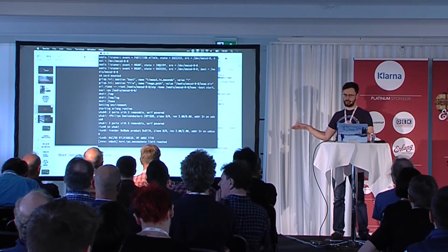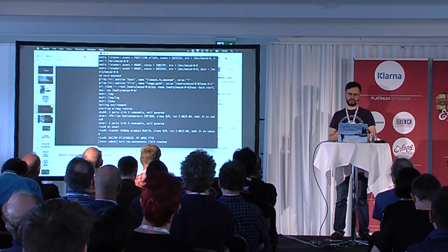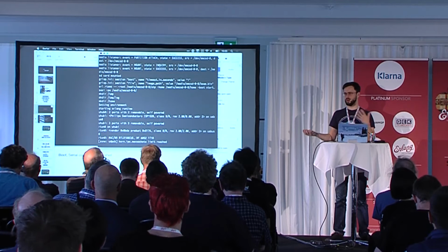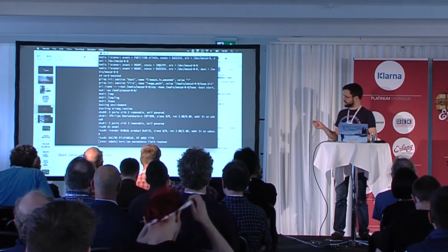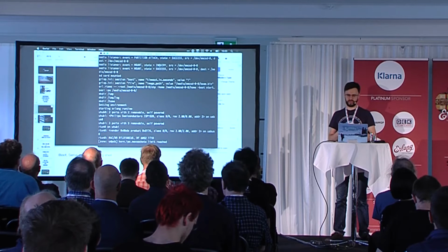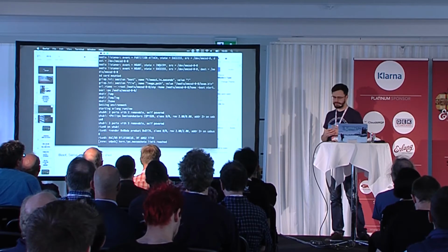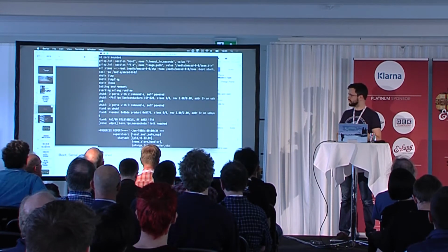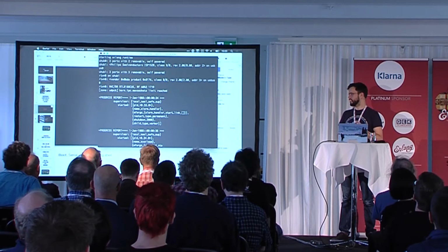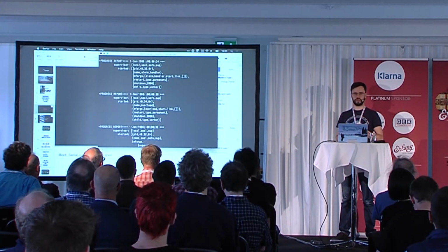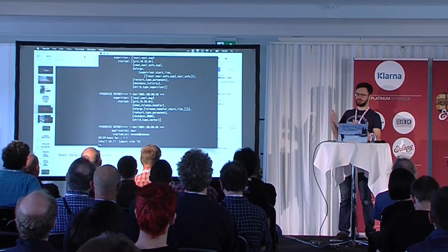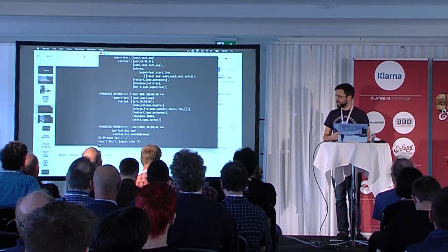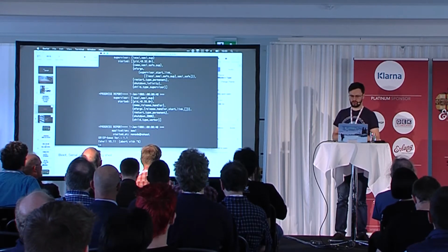This is the point where it kind of stops a bit. So what happens is that the Erlang runtime is started, and now it starts to load up the VM and load up all the OTP code. So in a short while, we'll see the SASL log start appearing, and then we're actually in real Erlang land. The reason that this is a bit slow is because we're still working on the SD card performance. Currently, we don't have any direct memory access, therefore reading from the SD card is a bit slow, and Erlang is kind of fighting a bit with the I/O, reading from the card and printing to the serial console. But we are booted.